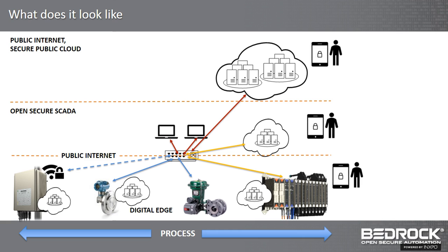It can be wireless, it would be secure, it can be twisted pair, it can be copper, it can be fiber, it can be Ethernet, it can be HART, it can be Profinet, DeviceNet. It doesn't really matter, because all of the connectivity needs to be able to mix and match, and it does. We've been doing this for decades. We know how to do that. And where there's non-Ethernet like twisted pair, obviously they connect through the local gateway device, and immediately you get to Ethernet.